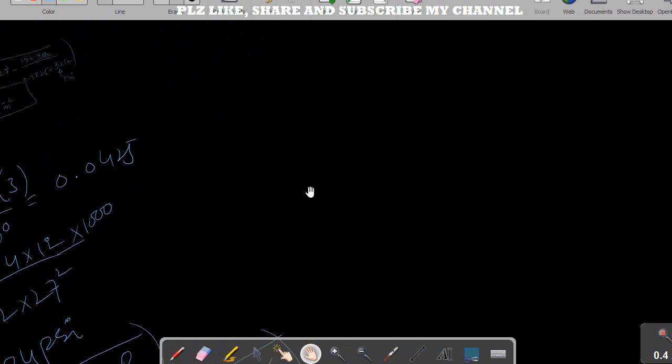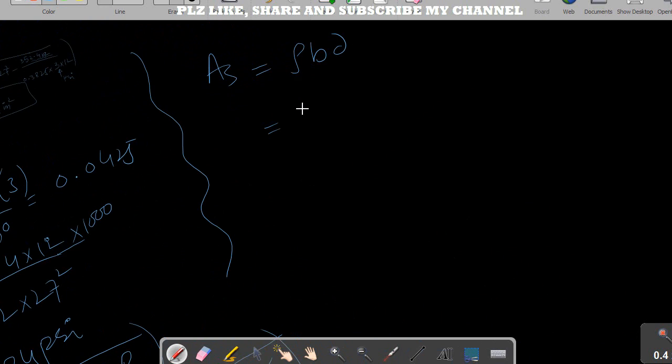I will calculate the area of steel, which is A equals rho b d. So we know the value of rho, which is 0.0102. We have already calculated d, 27.